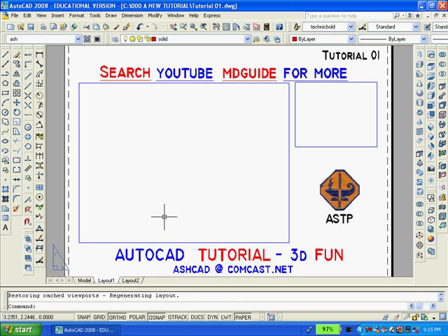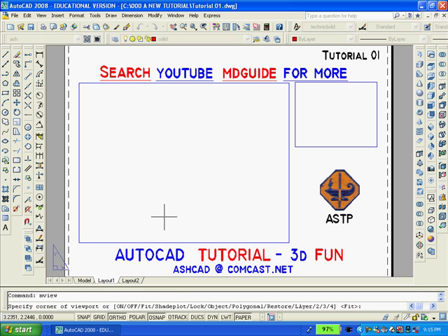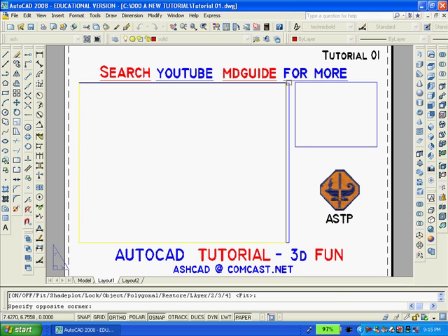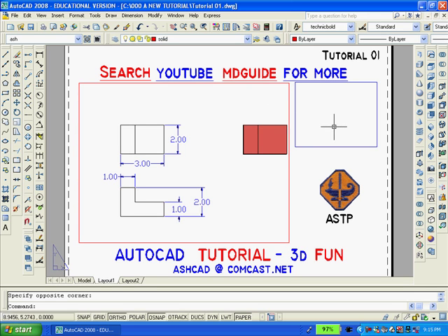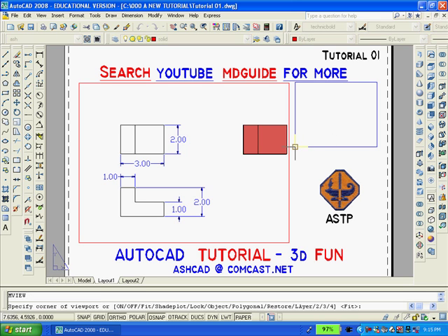As you can see, I had already created a couple of rectangular blocks that can be used as a guide for when I create the two viewports. Therefore, what I'll do now is to type MVIEW to create a viewport. Select one corner on the large viewport, and then I'll do the same. Hit enter to repeat the command and make another viewport.